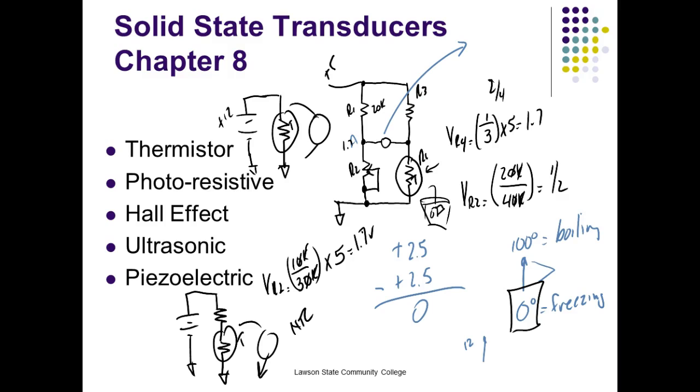It would be easy for a computer or something to convert that over to a temperature, right? So now we would have so many volts per degree. So we use Wheatstone bridges. Just about any device, if I'm going to have to set an origin, or a zero, on these sensors that change their resistance with temperature, I'm going to use a Wheatstone bridge, or they're going to use a Wheatstone bridge. And we've got all types of transducers that change their resistance relative to what they measure. But we've got to start off with an origin.